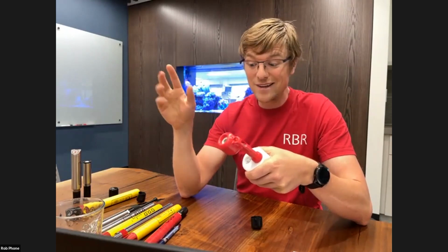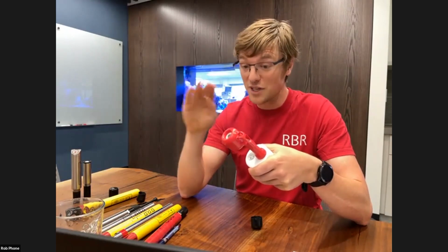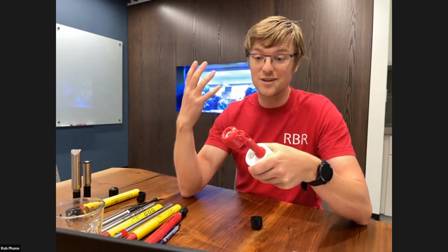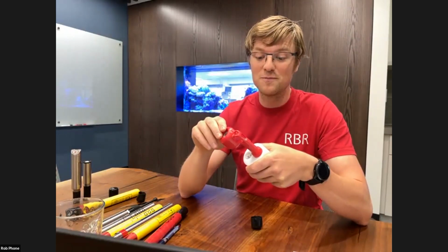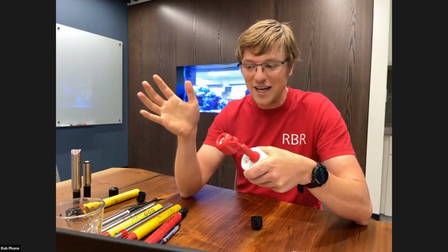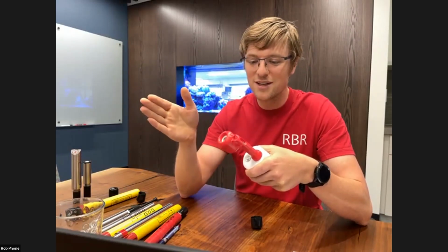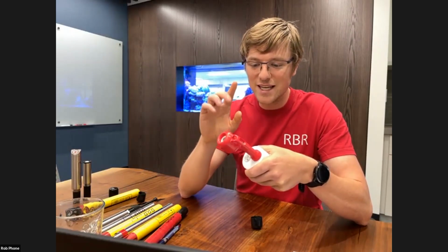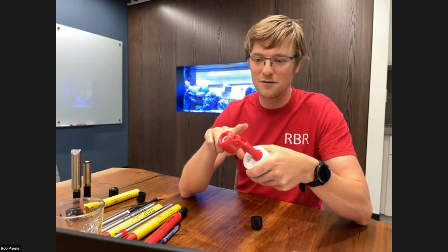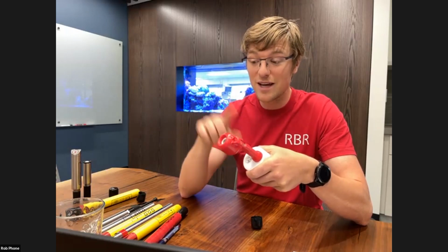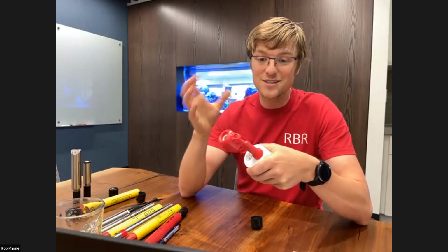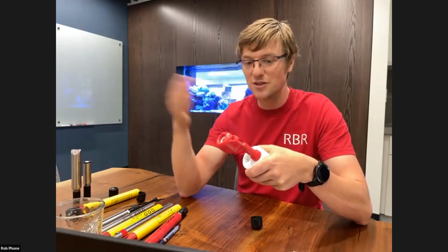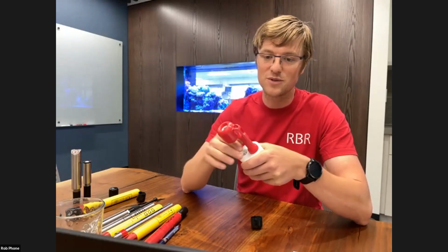So if you are in an environment with very sharp thermoclines, you would want to adjust your speed so that you can resolve that thermocline. So we don't have sort of a hard, fast value for you, but I think taking into account the time response of your slowest sensor and how sharp of gradients you would expect in that environment can start to give you an idea of how quickly you'd want to be profiling through that region.